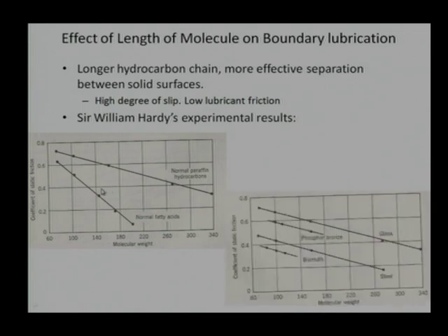There is another experiment, which shows that this kind of lubricant also depends on what kind of material is used. If you use bismuth, the coefficient of friction will be lesser. If I use phosphorus bronze, in that case the additives will not give such significantly good results. They have different chemical structures, and the bonding to phosphorus bronze may not be as good as the bonding between bismuth and the additives.